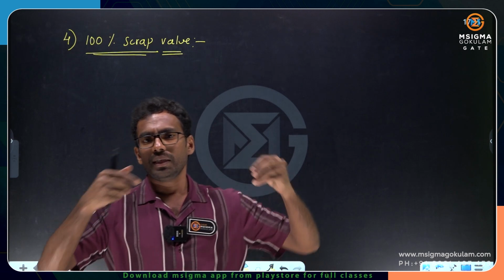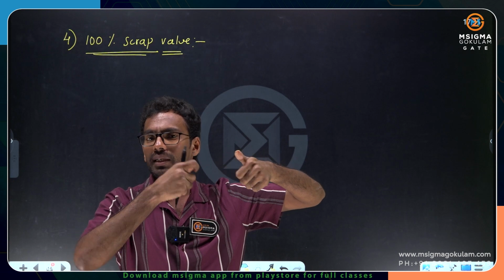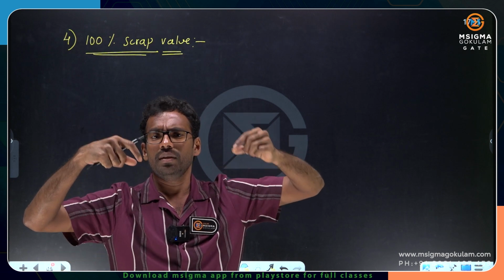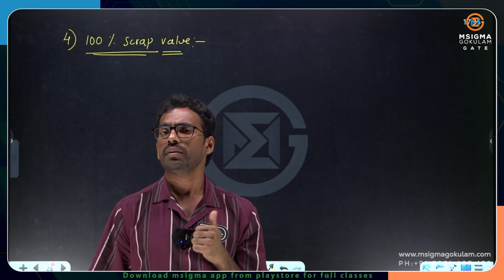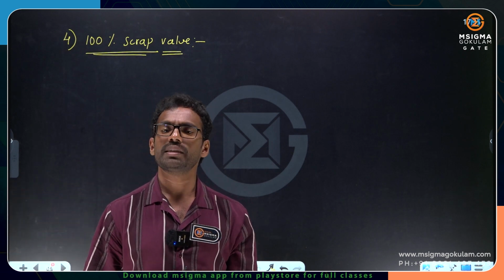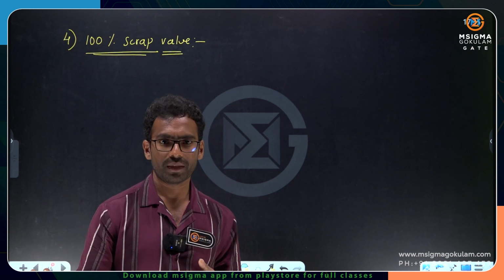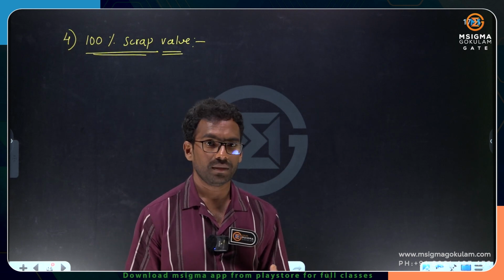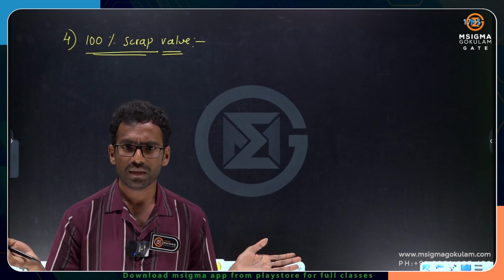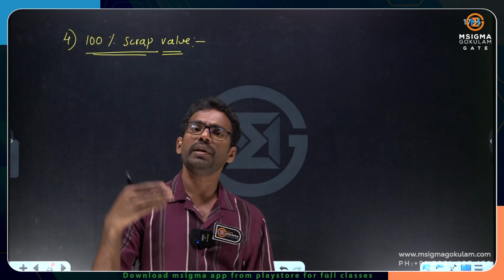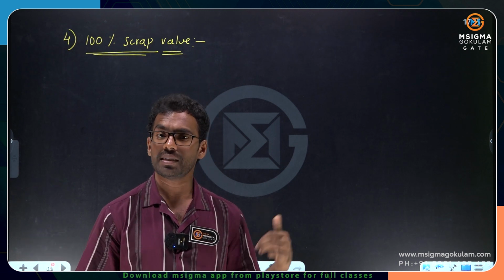Then you want to shift that particular steel structure from one place to another place. Very simple. Remove the bolt material in the connection, take the section and use the same section at some other location, and you construct the same kind of shed. That is possible in steel structures because they are transportable from one place to another. But once you dismantle, especially in case of RCC structures, that's it. When you dismantle it, it cannot be reused at some other location in case of RCC. But that is not the case in steel structures.